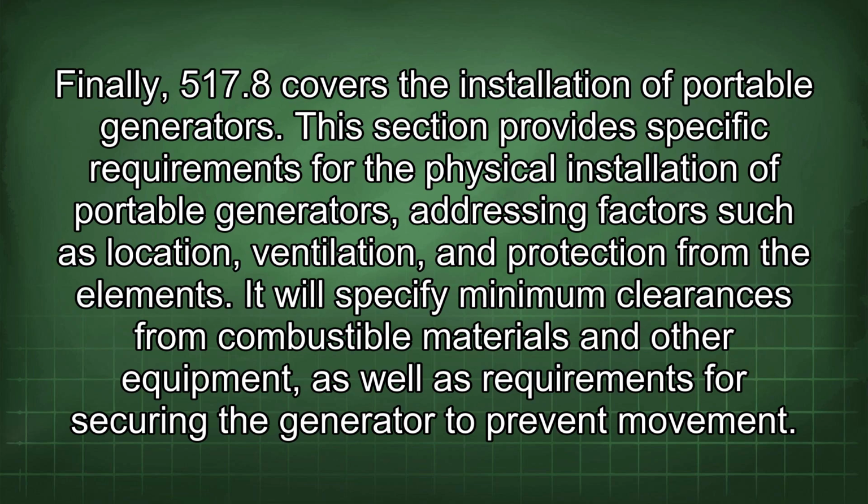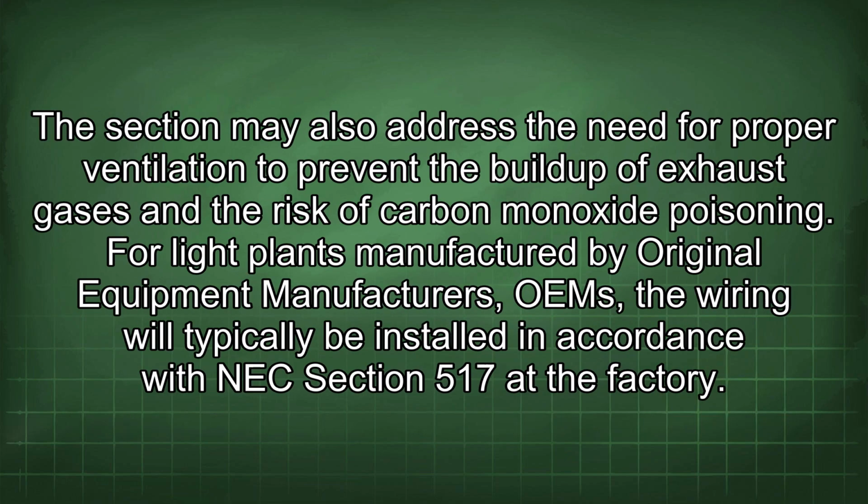Finally, 517.8 covers the installation of portable generators. This section provides specific requirements for the physical installation of portable generators, addressing factors such as location, ventilation, and protection from the elements. It will specify minimum clearances from combustible materials and other equipment, as well as requirements for securing the generator to prevent movement. The section may also address the need for proper ventilation to prevent the buildup of exhaust gases and the risk of carbon monoxide poisoning.